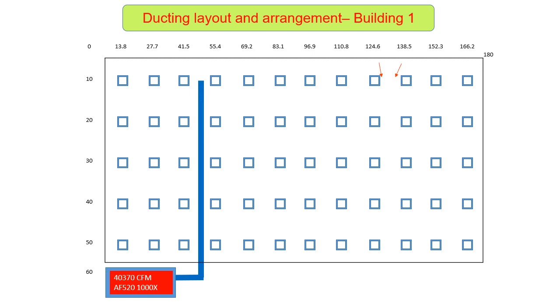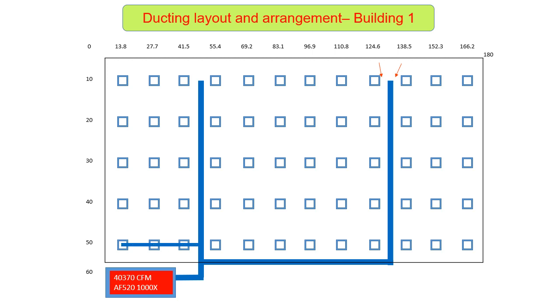To have the arrangement of the diffusers, and also to see what is a suitable location for the main duct or rigid duct, so that you can plan where is the main duct and where is the branch duct, so that all diffusers will get the even distribution of air.